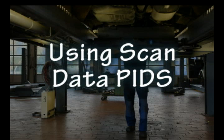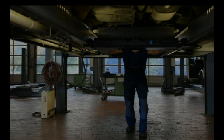Once the possible causes have been identified, it's time to select the appropriate data PIDs to monitor while verifying the problem. This is a very important step with this platform, as there are no codes. Failure to understand this will result in a long diagnostic process and unneeded parts. So let's consider these data PIDs for our test drive.